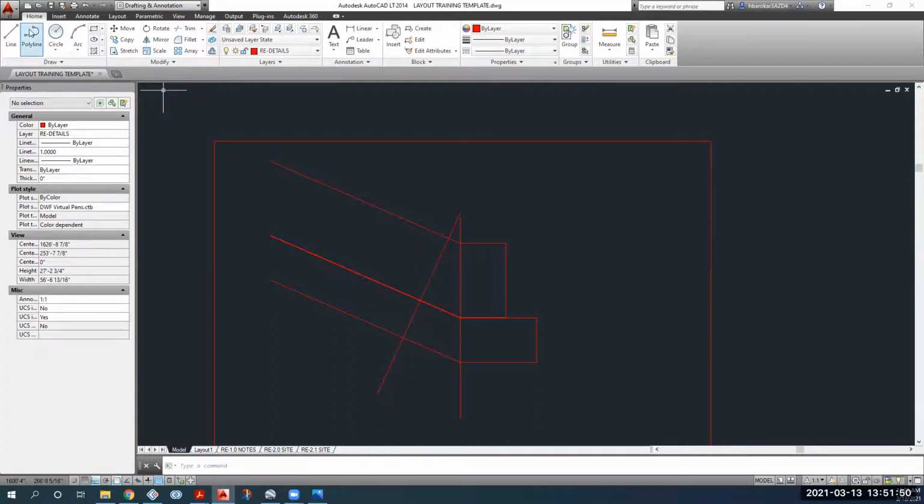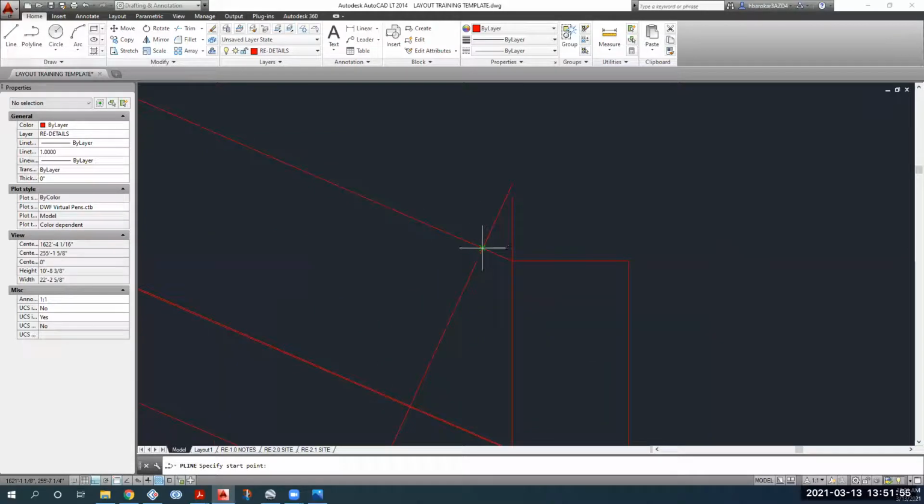So now I go to polyline and then I trace that rectangle here. To do that, I press here at the intersection, then I hover over this line, press 40, enter. It basically puts a line 40 inches away. Then I snap it to the other corners. So this is all going to come by practice, guys.